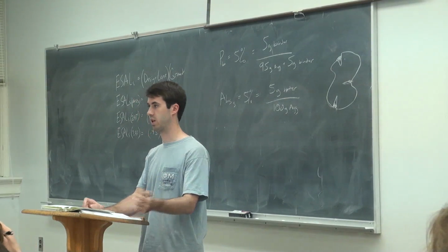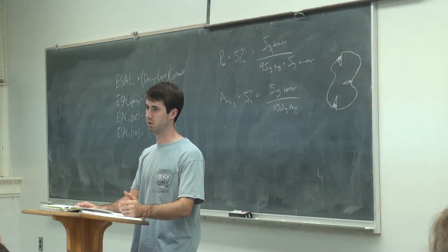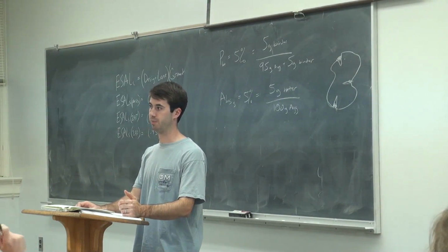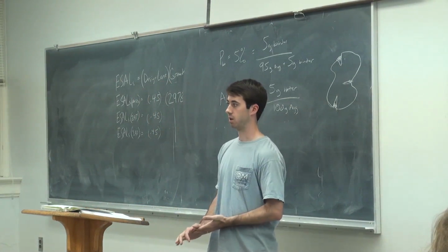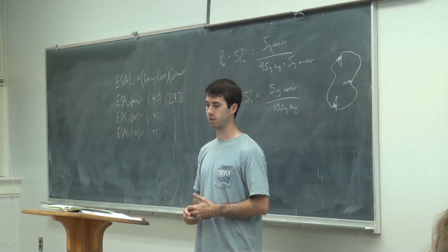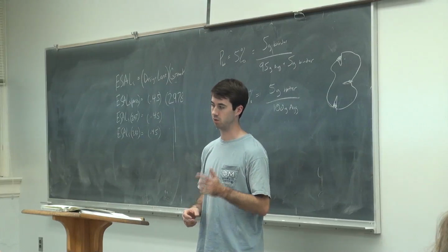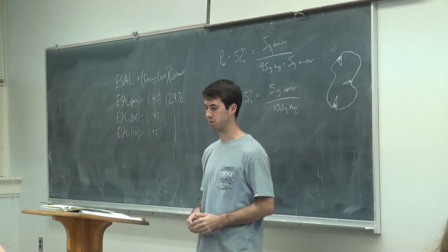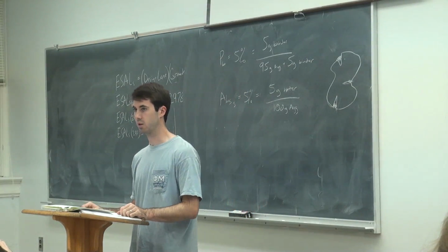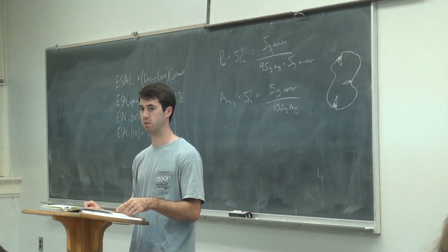So when you design an asphalt mix, you design to how many % air voids? 4. So basically the idea behind Superpave is you pick all these things, your gradation, all this stuff, and you run it to the design gyrations, and you want to adjust the binder content so that you hit 4% air voids.